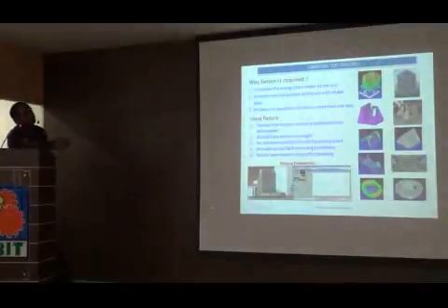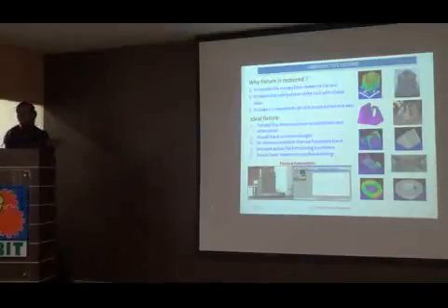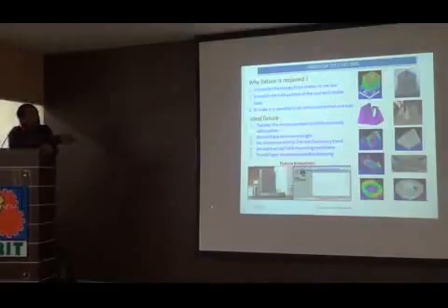Right. So apart from the shakers, as I mentioned, you need some vibration testing elements like fixtures. So what is a fixture? A fixture is an intermediate component between the shaker and the unit to be tested. It has to faithfully transmit the energy from the shaker to the unit under test. That is its main purpose.